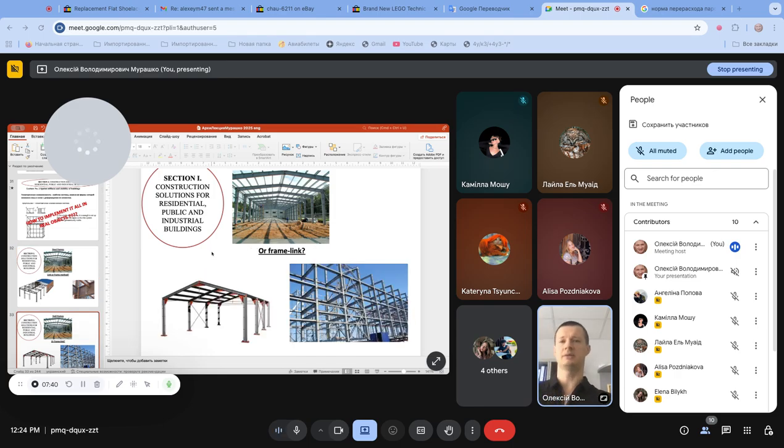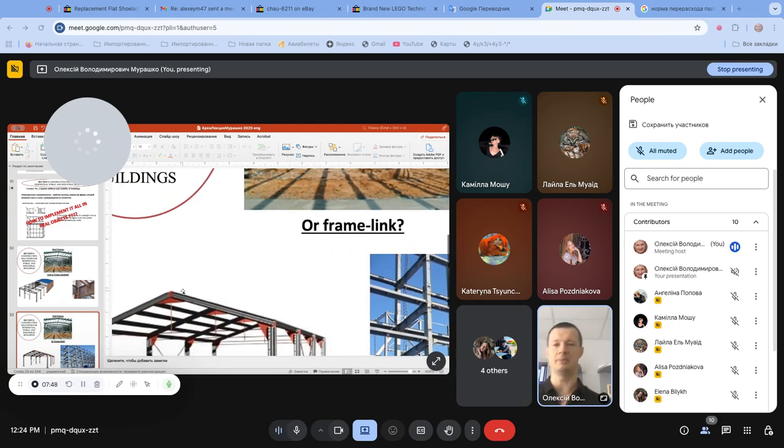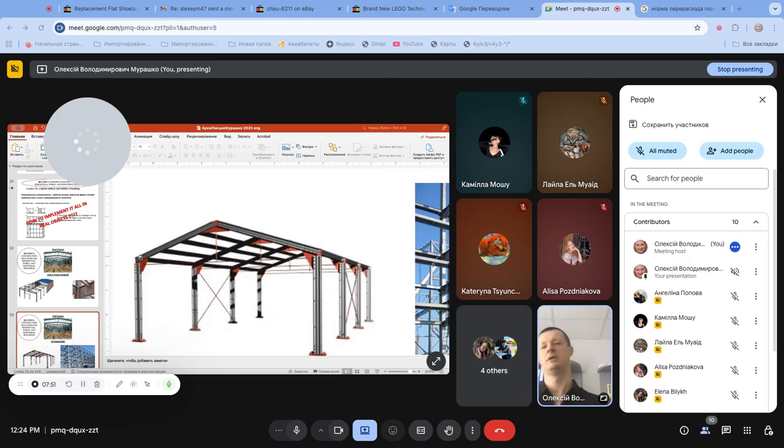So, some examples. Same situation. In this direction, you can see these special triangle elements, which add rigidity to the connection of these column and beam elements, and this makes it work like a frame in this direction. Along the building, they have added these crosswise arranged links, and as I told you previously, it is enough to add one link in one direction.